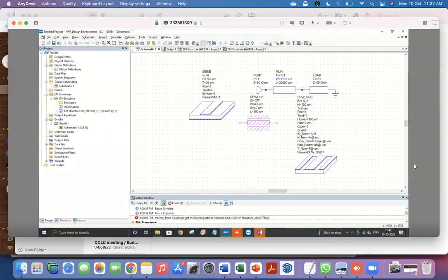So last time we looked at the pre-solved physical models as an alternate way of defining transmission line sections in Microwave Office. These allow you to do slightly more realistic simulations when compared to the ideal models which we had seen earlier. Those are the electrical models. So the electrical models don't care about what the material is, what the substrate is, what the dimensions are. It just gives you the simplest model for a transmission line, which is basically propagating the phase along the length of the transmission line.